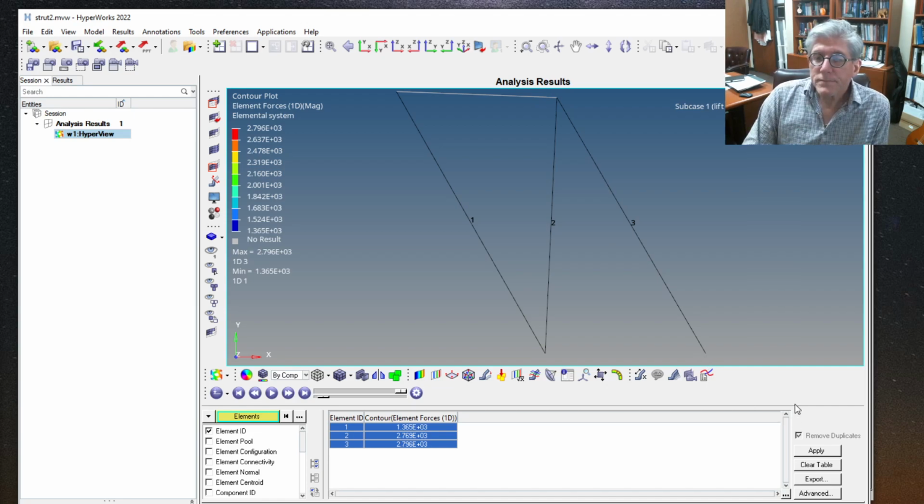All right, so there you go. We've done our first finite element model. We made it out of these C-rod elements, right? We made the model by defining the material, the properties of the C-rod elements, and then the elements, applied boundary conditions, done a load step, solved it, and now we've looked at the results.